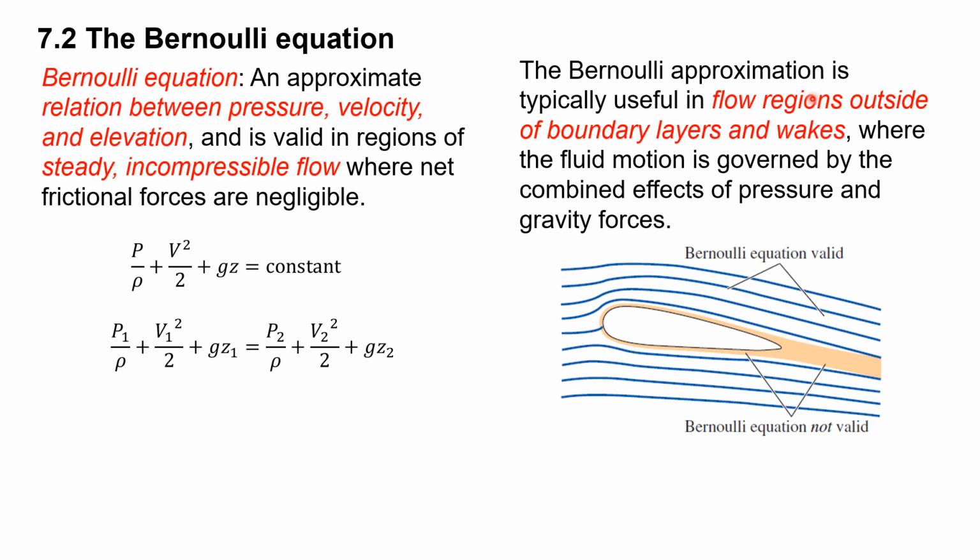Bernoulli's approximation is typically useful in flow regions outside of boundary layers and wakes, where the fluid motion is governed by the combined effect of pressure and gravity forces. From this picture, we can see where Bernoulli's equation is valid and where it is not valid. Let's say you have a flow region, which we call a wake.